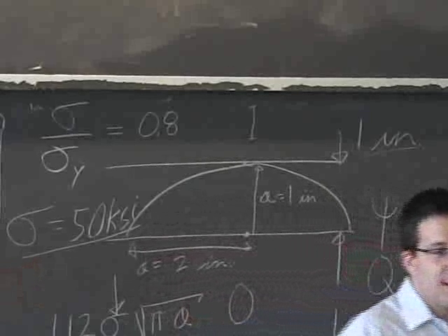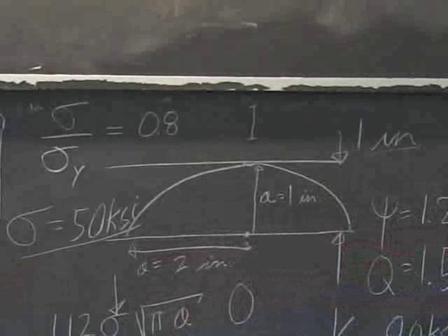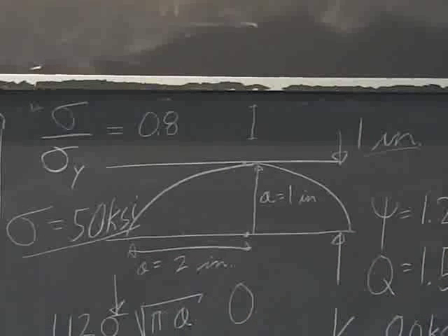So I quickly get to a much greater thickness, on the order of 6 inches. And that was using pretty much the mildest steel I could find. It would have a fracture toughness around 200 KSI square root of inch and a much lower yield. So there's no way you'll reach a higher value.